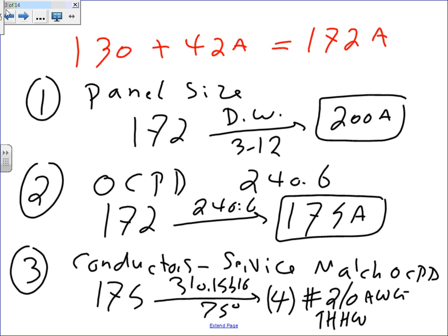I think you're right. So the conduit here, guys, I always like to put the conduit. You're not a designer if you don't size the conduit with everything. So 1 conduit, 2-inch PVC schedule 80. Why schedule 80? Because we're assuming physical protection. Service is a good assumption. Service is a good idea to do that.